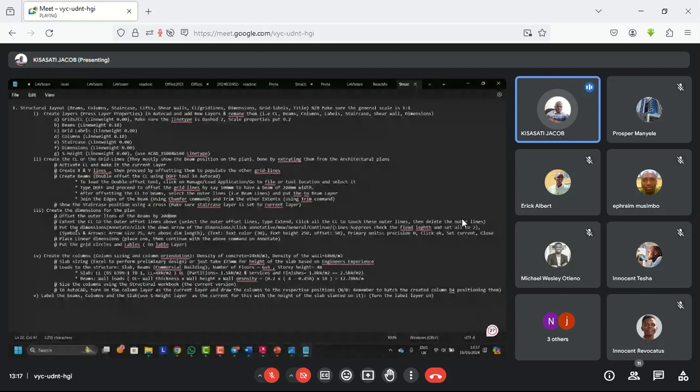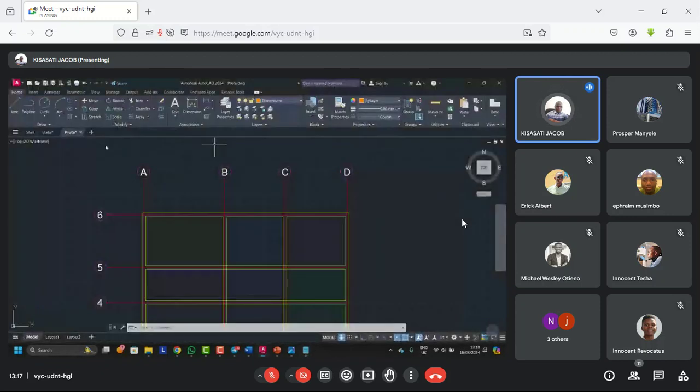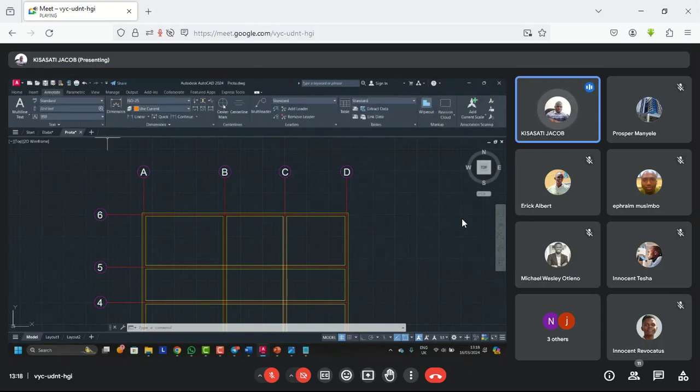Now, to set the dimensions, this is the procedure. This one is very important. First of all, we'll go to annotate, then do all these settings. But now, I want us to pay attention to the color. So after turning this layer on as your current layer, the next thing is to come to annotate. This is where you'll do all the important settings for the text and all other things.